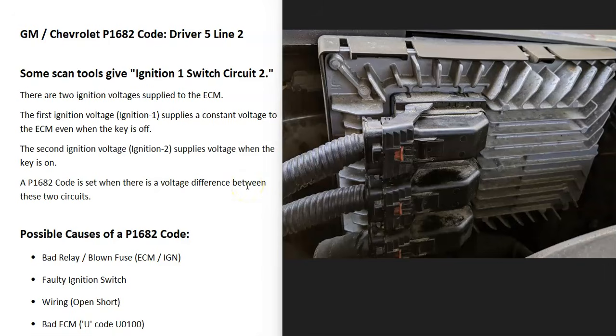And the last thing on the list is going to be that the engine control module is having an issue. And this isn't too common. Usually it's going to be something else. It's going to be inside the wiring or a bad ignition switch or something like that. But it is possible that it's gone bad.